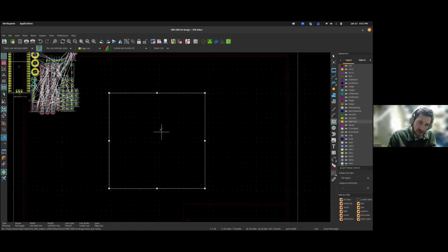So by sticking to this size, which is big enough for this project, we can get a 4-layer PCB for about $1, $1.50, maybe $1.80 per PCB, which is a really good price. A 2-layer PCB of the same size would be 90 cents. So it's roughly a doubling in the price, but it offers a lot of performance advantages in terms of noise.